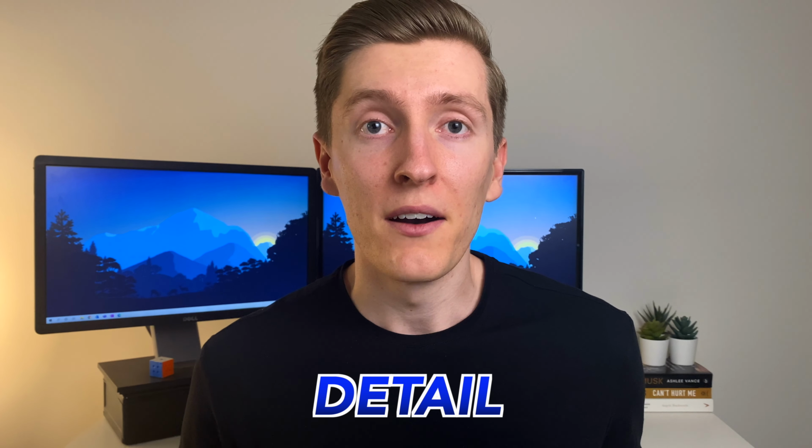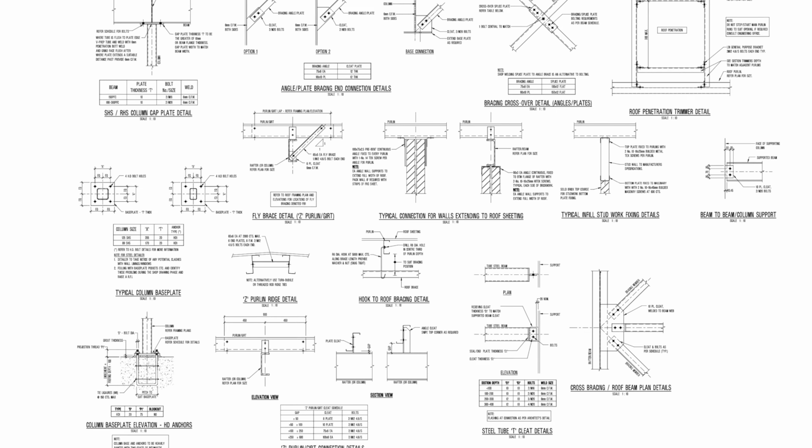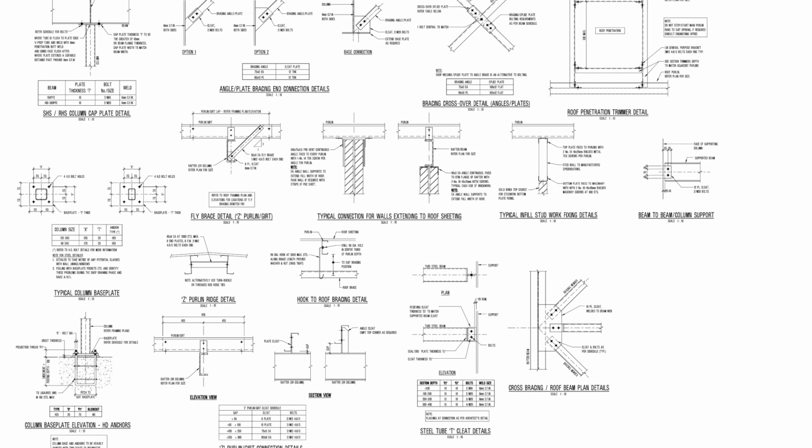Alright, and the last way things are displayed is through something called a detail, and a detail is used to show more specific information in a particular area. A couple of these areas can be at places like at a concrete joint or at a steel connection, and some of the more specific information that can be shown are things like dimensions, reinforcement bar size, and bolt and weld configuration. Also, a lot of companies tend to have a set of typical details which they reuse on projects, so you will get familiar with these ones over time.